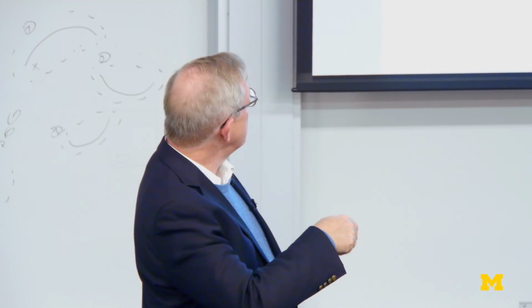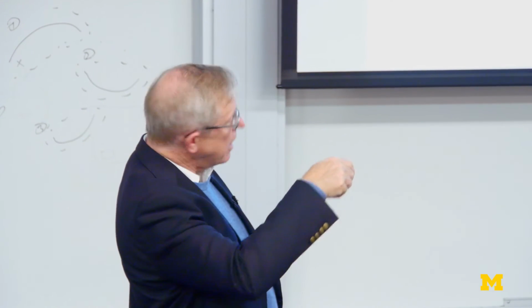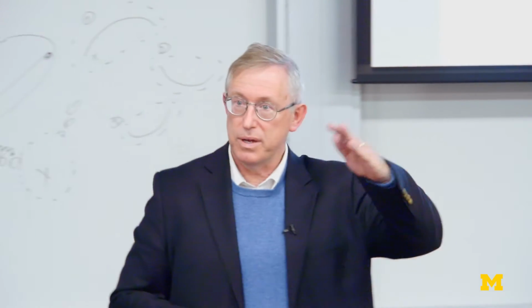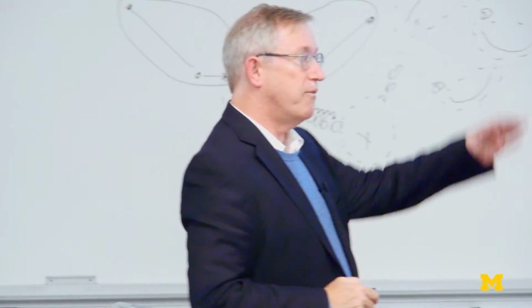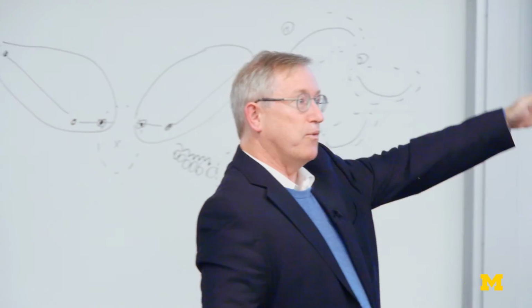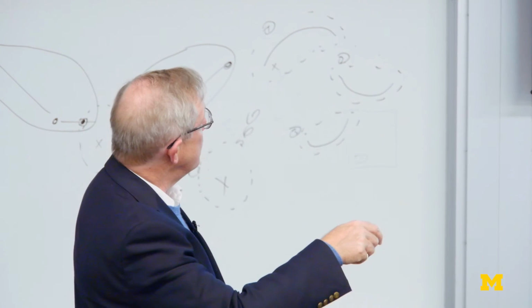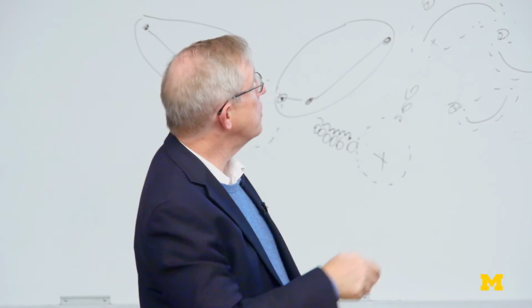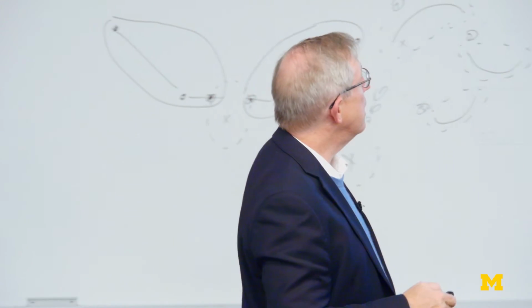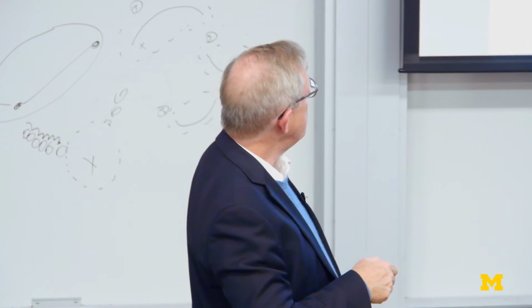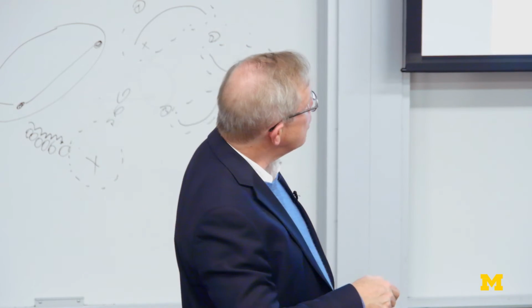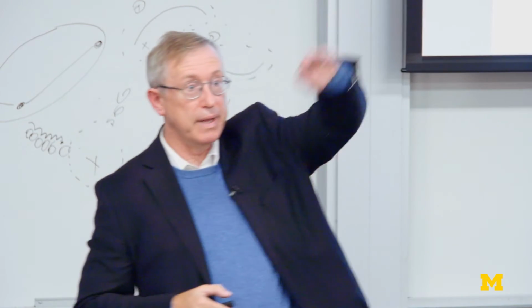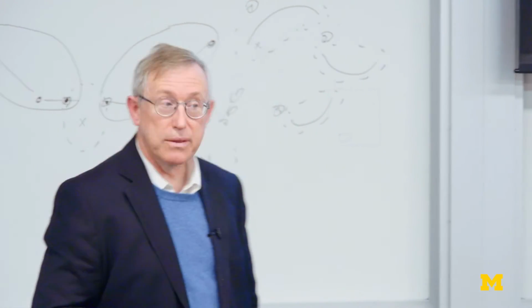In recent work, we found that the AWGN channel capacity is an upper bound for a fiber optic channel, or at least a split-step Fourier model. You can't exceed this under some reasonable hypothesis. Various lower bounds all have that form of going up and then coming down again. Those are the achievable rates.